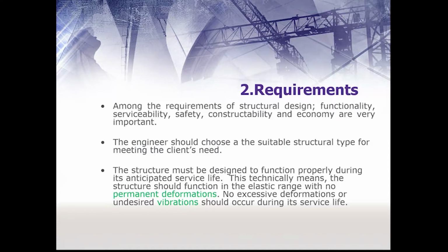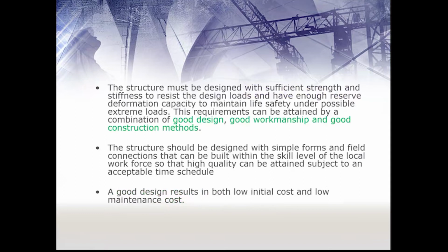This technically means the structure should function in the elastic range with no permanent deformation. By permanent deformation, I mean deformation that is not reversible. No excessive deformation or undesired vibration should occur during the service life either. All the structures that we design, we make sure that they function in the elastic range.